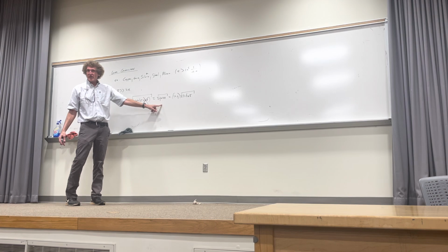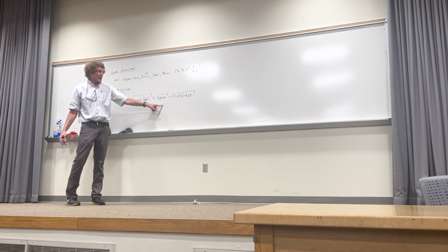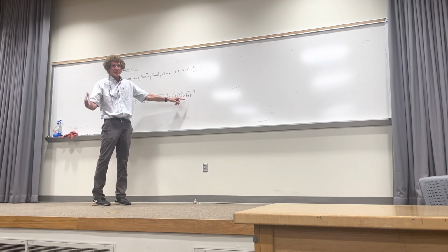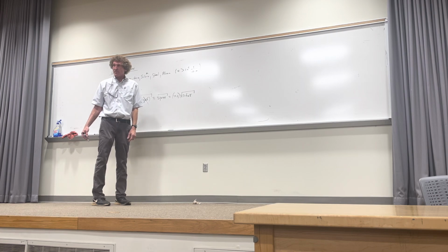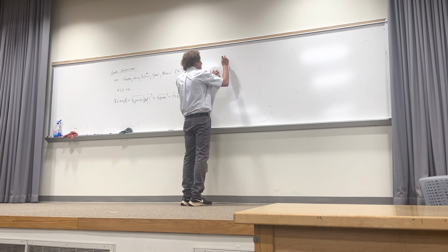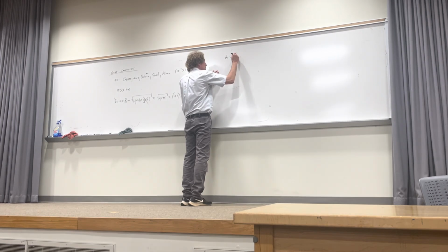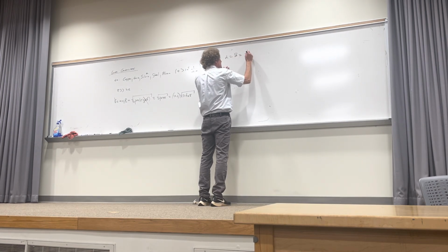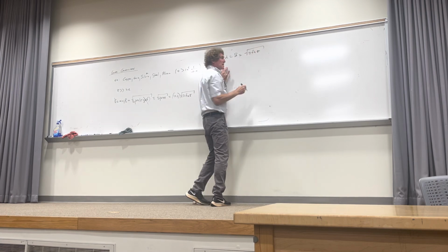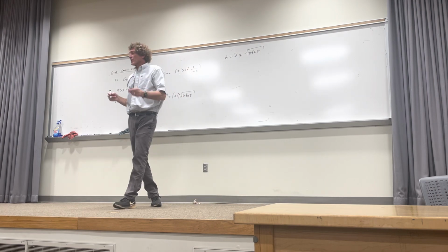Well, the square root of j we talked about is what? It's really (1 plus j) over the square root of 2. Do you all remember that, class? If you break that out, then you get the square root of 2, omega over the square root of 2, which, since omega is 2 pi f, is just pi f mu sigma. You all follow me? And that means one thing that's very important. For a good conductor, you will have alpha equal to beta, and that's equal to the square root of pi f mu sigma.